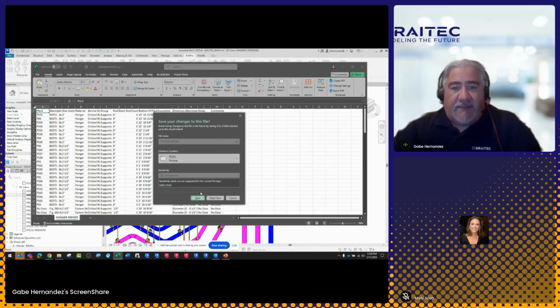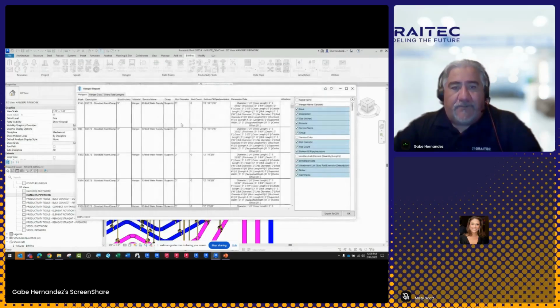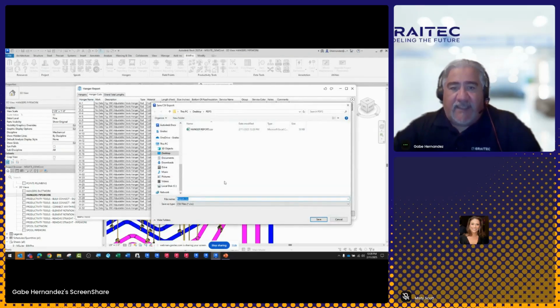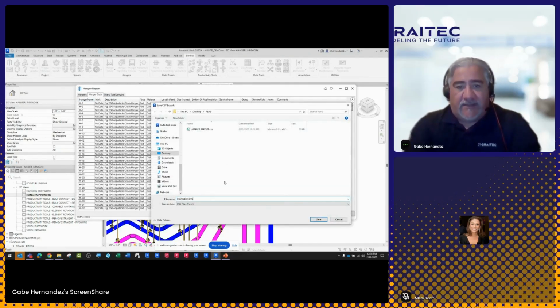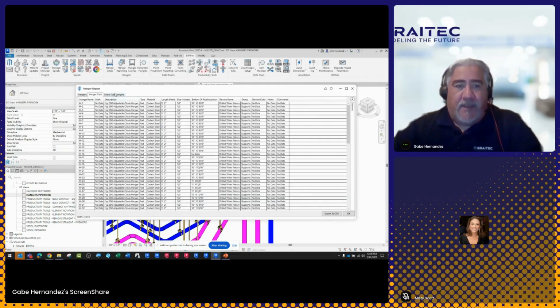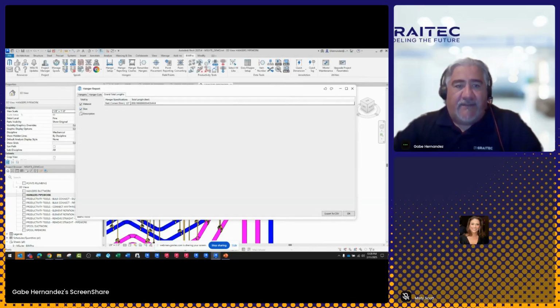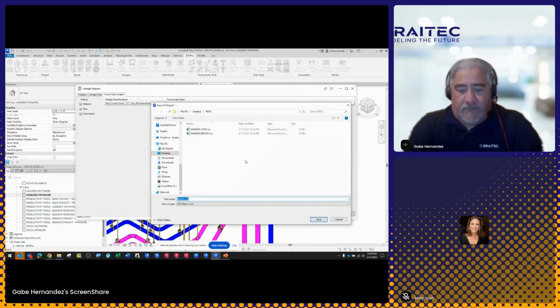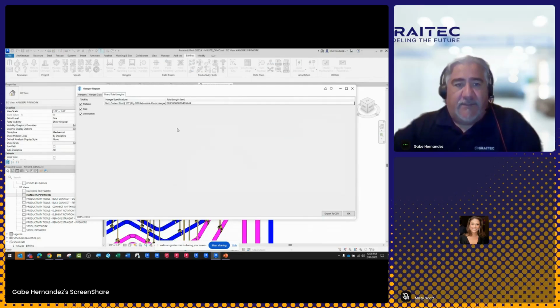Okay. Same thing for the hanger cuts, right? I can go in here and do the same thing, export this out if I want to customize that. So say hanger cuts. And then you even have your total links here, material size and description. And then I can export that as well out of here. Okay. So you can do quite a bit with your hangers and your reports.